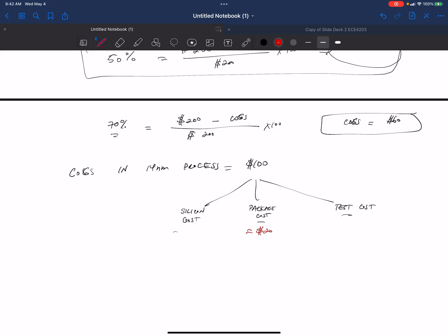If I was going to make this presentation, I would put some assumptions there: high pin count, high power dissipation, but not military or slow or exotic. Okay. Now the test cost, I think a good estimate is that I put in $20 for a test cost. Again, it's a big chip. My estimation was that typically the price per test system is $150 per hour. And I said, okay, it would take about 10 minutes to test this part.